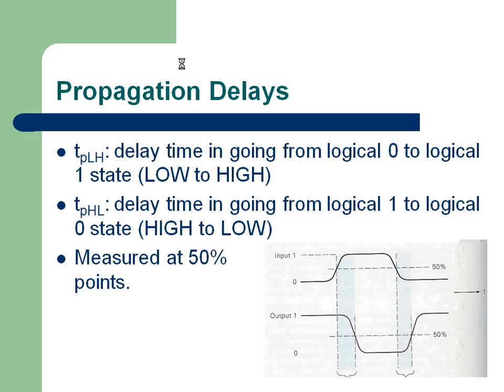However, if it is not driving all of them, only some of them, it will take less time than T1 only. Got it? So that is the reason the propagation delay is also discussed in addition to the driving capability, because as a combination that becomes a trade-off. You may have more fan out at the expense of taking more delay. Got it? See, same current is there.